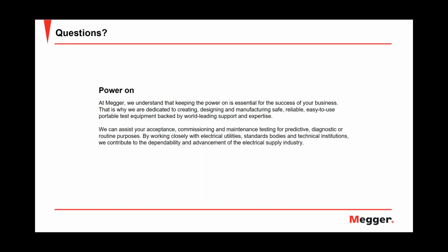Okay. So why do open conductor faults happen in the case of aluminum only and not with copper? Well, it's simple. Aluminum has a much lower melting temperature than copper has. Normally, where these failures, the open circuit, or what we call burnt in the clear failures, happen is when you have a circuit and there is a little bit more resistance at the point where the fault is in the conductor, but it's not enough to trip the fuse or the breaker.